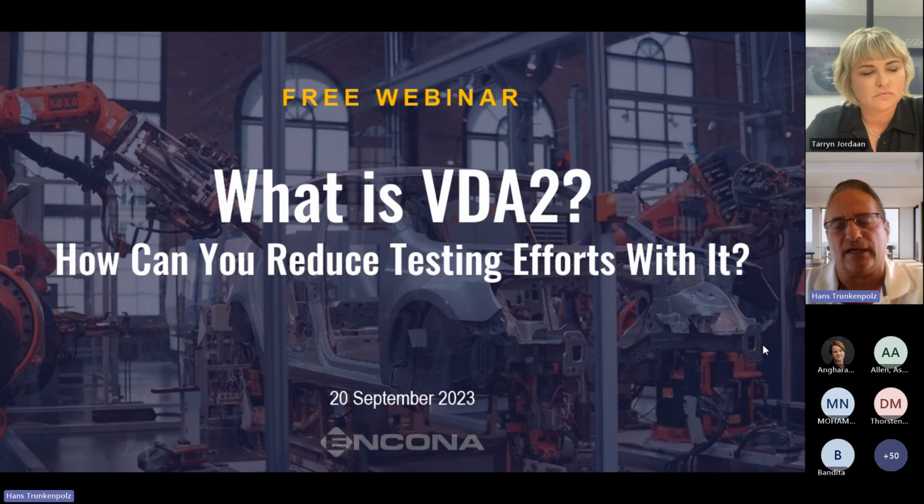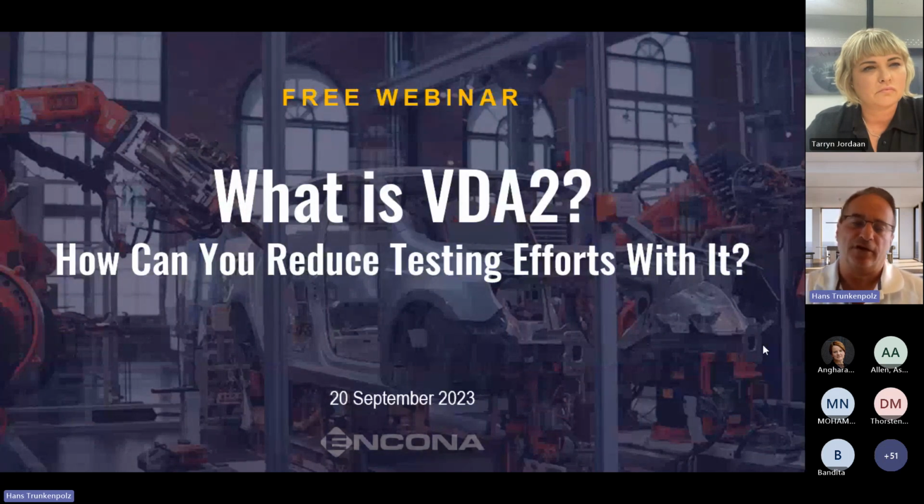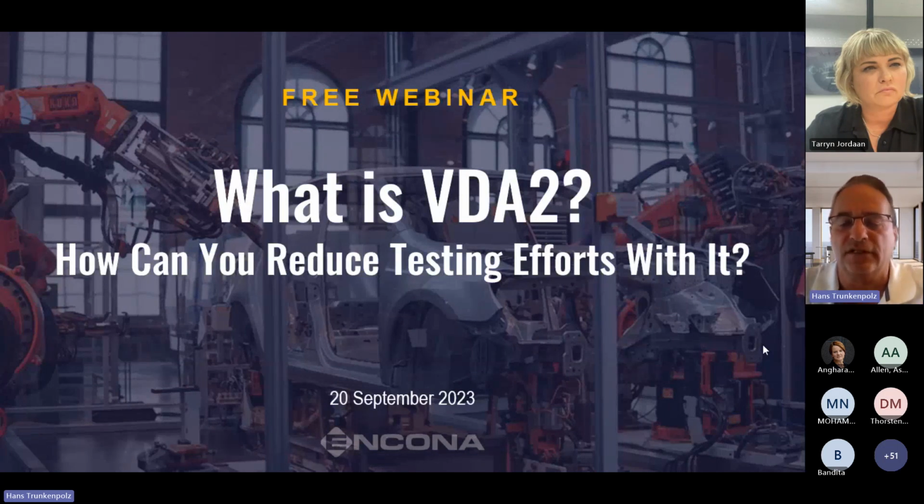And that's why we have today a differentiation between the AIAG, which is the PPAP that you just mentioned, the production part approval process, which has generally 18 submission requirements. And then you have the counterpart for the German car makers, which is the VDA 2, and they call it the PPA procedure, which is the production process and product approval. Very similar. The intention is the same, to get for every supplier a final approval so that the supply chain can shift into serial shipments of their products. Okay.